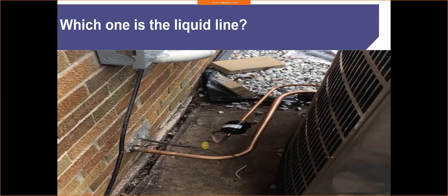And by doing so, we may start to form condensation around the area. All right, we remove the heat from the air. That air lowers the temperature. It can't hold as much moisture. And now all of a sudden, we start to get condensation forming on our line. So we may develop leaks or dripping from our pipes, and we don't want that, especially if they're running behind drywall or anything like that. So insulation is critical on the vapor line.